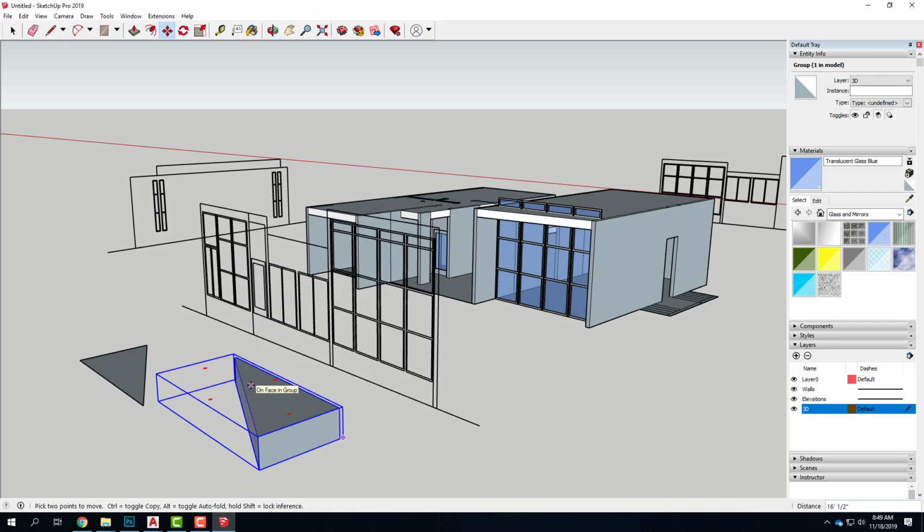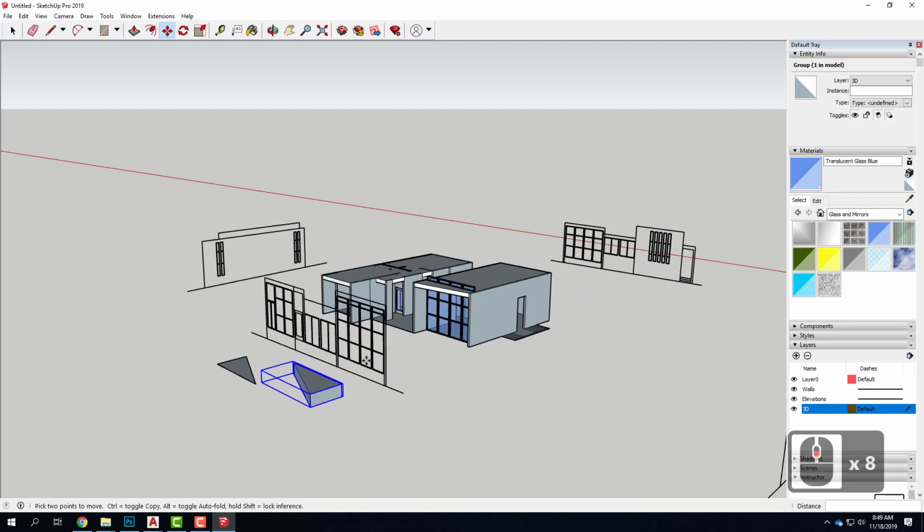All right. So I'm going to go ahead and let you guys start working. I don't want to keep using up all your time. Really, this is about modeling. I think most of you are pretty familiar with SketchUp and getting started. If you're not, it's okay. You will become pretty familiar with it pretty quick. There's not too many tools to worry about. Remember, delete the extra non-important AutoCAD layers. That's the most important thing you can take away with this: pare down your AutoCAD layers, start with the simplest group of lines that you can get, because it's going to end up being complicated if you don't. All right? I'll let you guys start working.